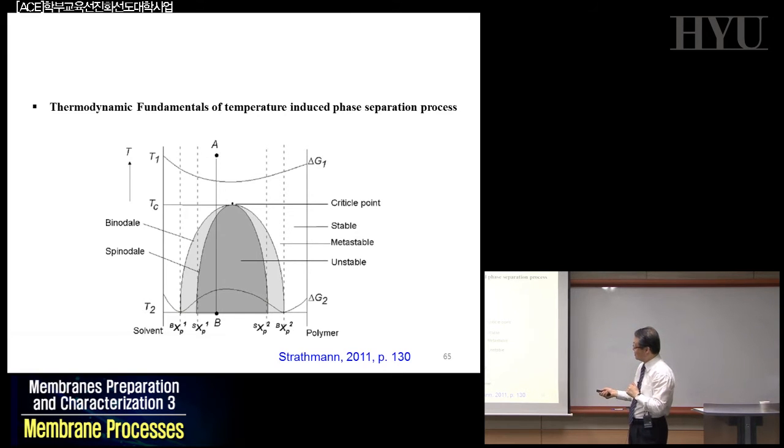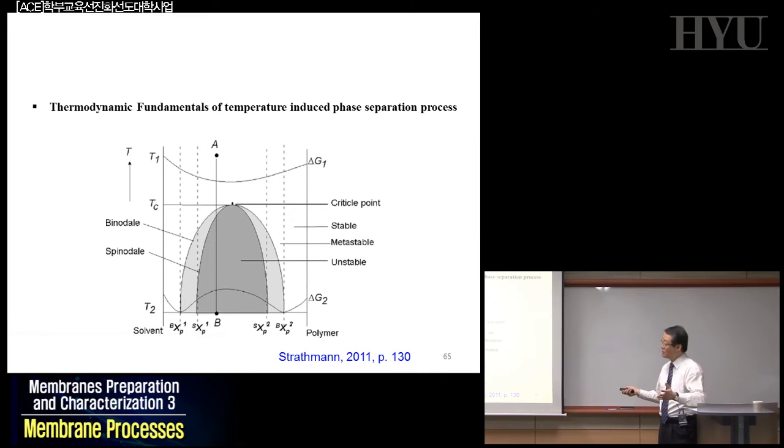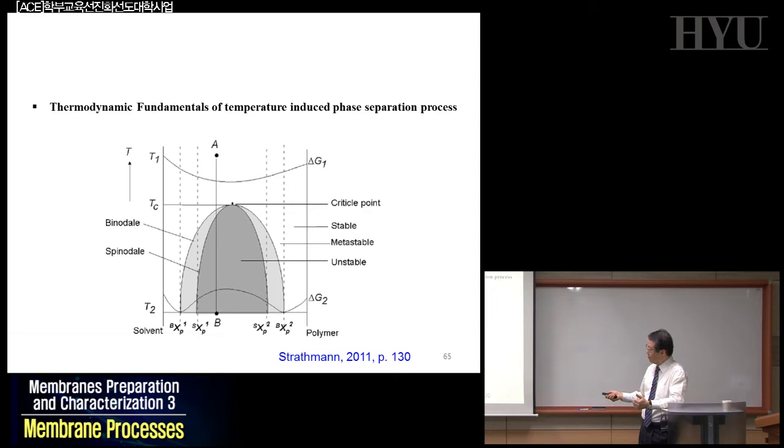But if you pass the other lines, something like this, then you form the nuclei, and by lowering the temperature, you have some time, because you always lower your temperature as a function of the rate of your cooling. Rate means time, so decreasing temperature will always take some time, meaning that you form the nuclei, and you have some time to grow your nuclei to become crystals, or polymers.